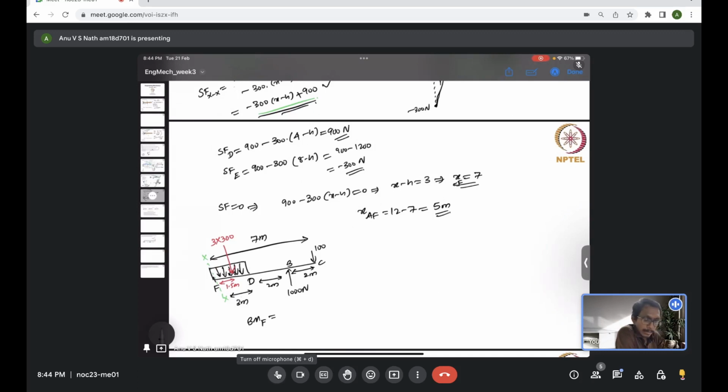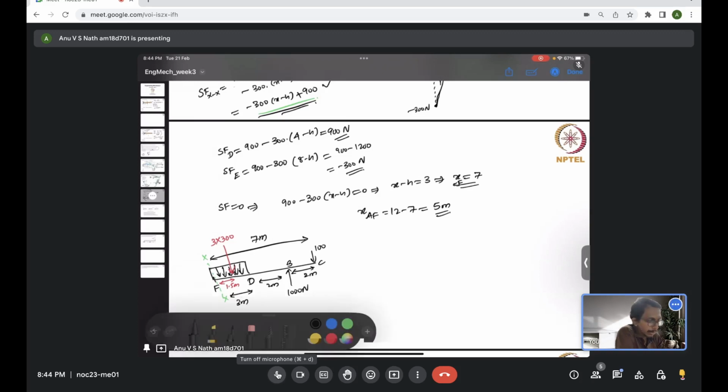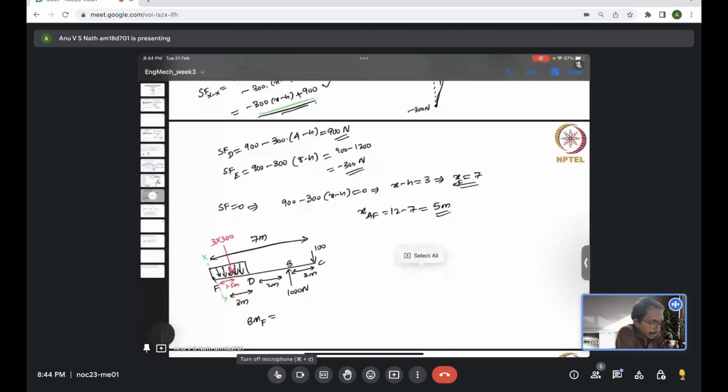So now we are considering only right side. It will be equal and opposite in magnitude, that's all. So at point C, 100 Newton is acting, which is 7 units or 7 meter apart, causing a clockwise moment. So I am taking this negative. Just a convention. You only need magnitude and just say whether it is counterclockwise or clockwise. Then 1000 Newton, which is acting 5 units from the end F, or from the section XX. So it's 5, which is in the counterclockwise direction.